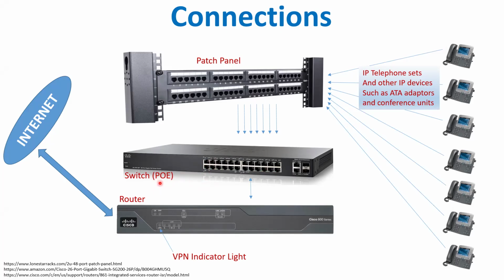PoE stands for power over Ethernet, which means that the Ethernet cable carries the data signal, and on top of that, there is a DC power, usually 48 volts, but there are some different PoEs that employ different voltages. So the specs have to be reviewed before you're installing the system.